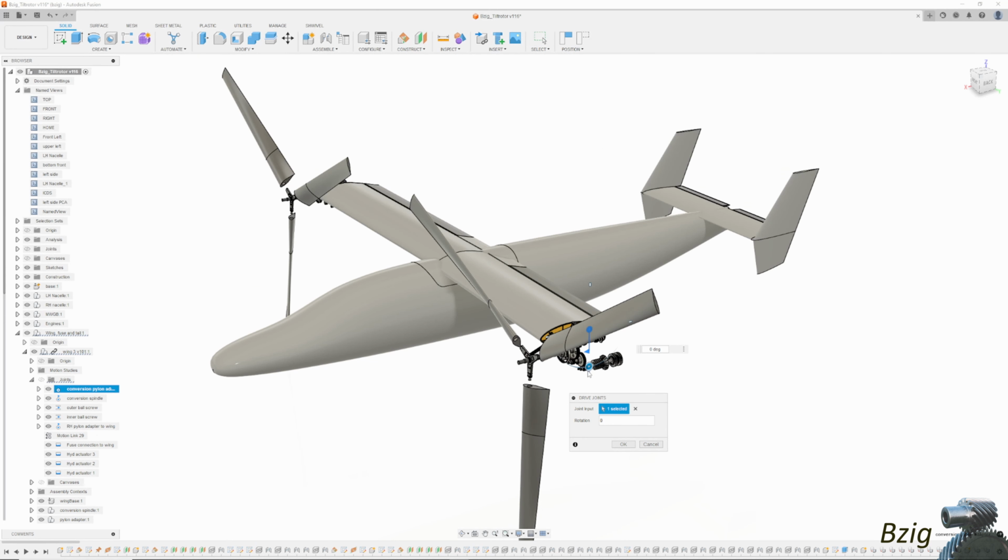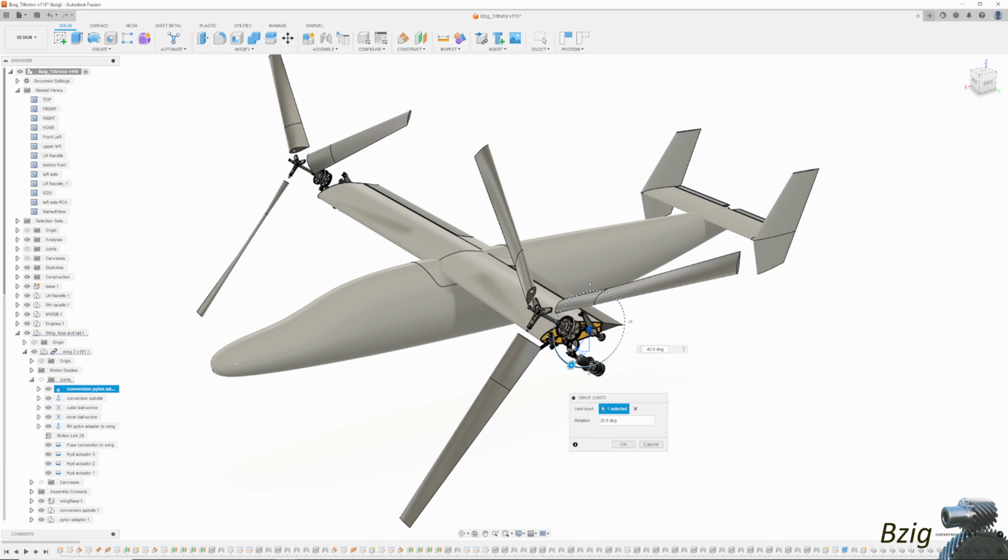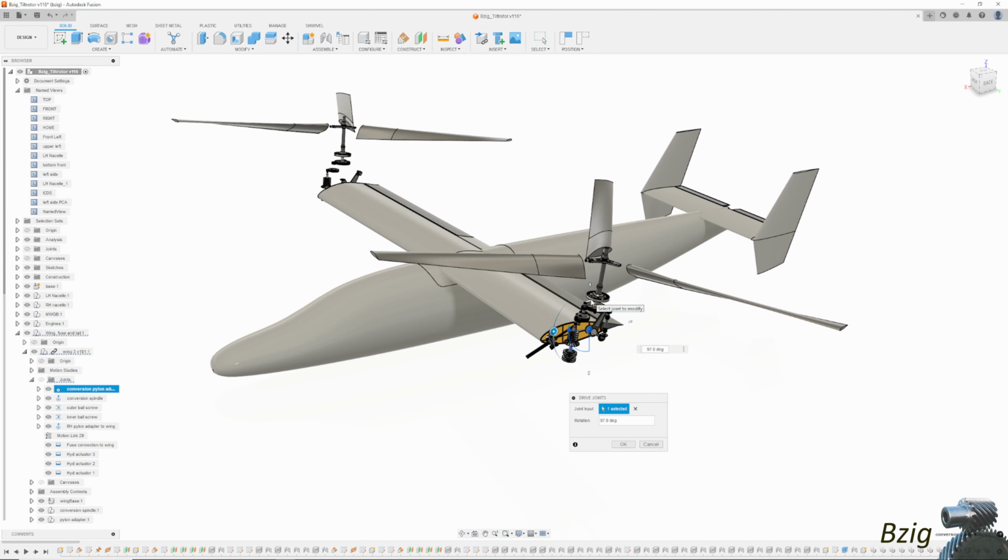The range of motion of this pylon conversion system is from 0 degrees in wing-borne flight to 97 degrees in thrust-borne flight. Motion past the vertical in a hover is useful for a few things. It allows more effective deceleration on the approach to hover, and it allows the pilot to decouple hover position and hover attitude, which is useful for landing on sloping terrain.